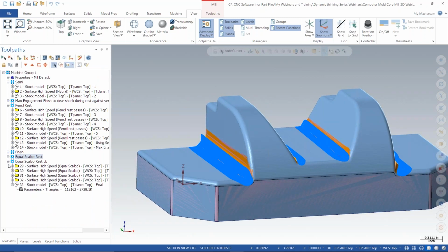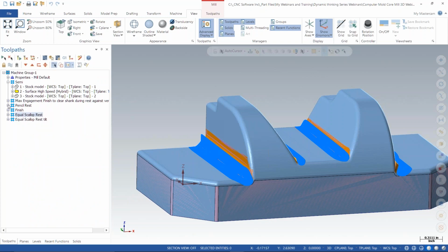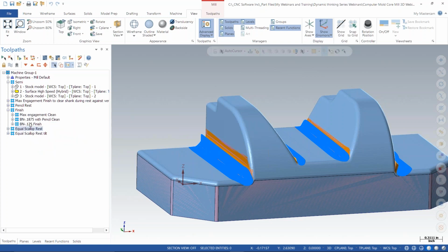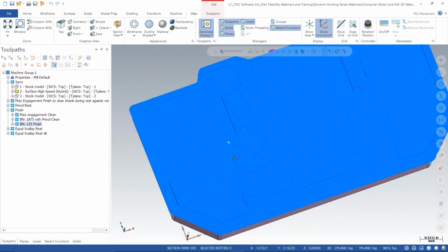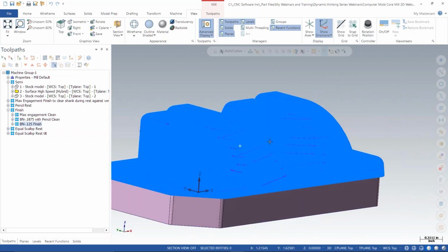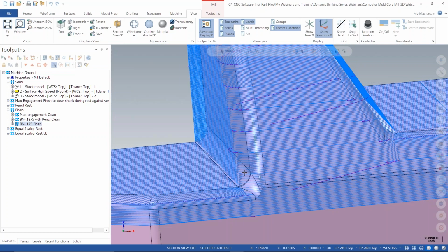So the reason that you want to dig these big corners out at times is because you're just trying to make your finishing safe. Here are some of the finishing routines that I might have been trying to accomplish. Maybe I wanted to just run the 1/8 inch on the whole part. I'm not saying you would, but I was able to clean this corner after the 1/2 inch, so I can rip this 1/8 inch on the whole part if that's what I wanted to do.